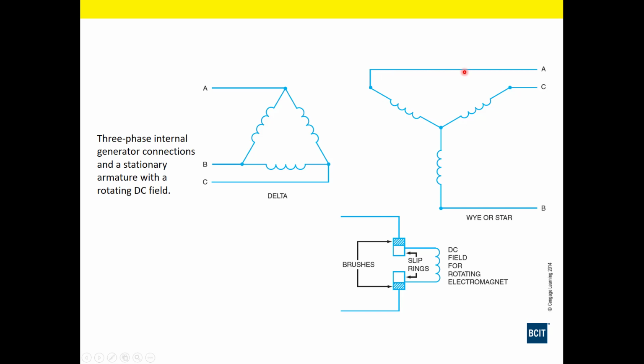But the currents are going to be limited. Now if we have it delta connected, and let's say this was generating about 4,700 volts, our current through this winding will be able to be higher to our loads because we have a delta connected system. So it's going to be specific to the application, or what design importance was for the person designing the alternator.